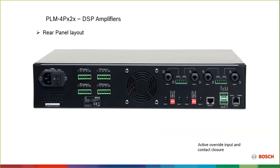So I get more features with the controller. I obviously get the wall controls and the call stations, but in short, for a very reasonably offered price, I could just buy an amplifier and then plug in a call station or a PTT mic and make an extremely budget-friendly paging system and background music system just off an amplifier and a couple microphones and speakers for a smaller location. Of course, each output you can do a 4 ohm, 8 ohm low impedance output, and certainly has 70 volt and 100 volt if you're in Europe. So we give you all of those options to use with or without the controller and with or without certain third-party gear. I'll go to that next slide.